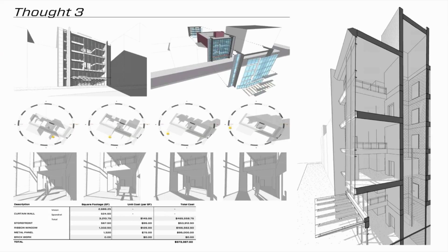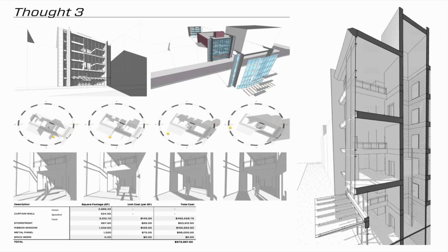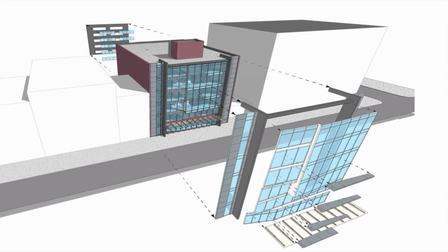So at that point, while the team is doing some facade studies, I may be switching gears, because it's always a divide and conquer approach. It's never really a handoff approach in the design process. There's a lot of things happening at once. I may be drilling in and getting information back in the FormIt model about developable area for the floor plate, and working with the teams to do test fits and get an idea of what we can fit inside this building on the floor, while at the same time further analysis and development of the building could be happening in FormIt, back in Revit itself, calculating areas of materials for build quantity and those types of things.